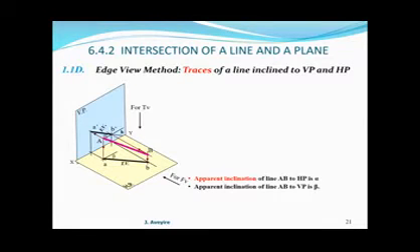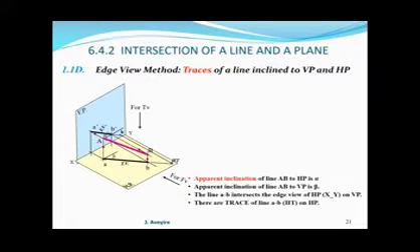Here we have H, which means that the line intersects the HP. To locate it properly, we draw the horizontal projector and then the extension of the line of TV, and that gives us our HT. We can prove it by taking the true line AB and extending it in that direction to give us the true HT.